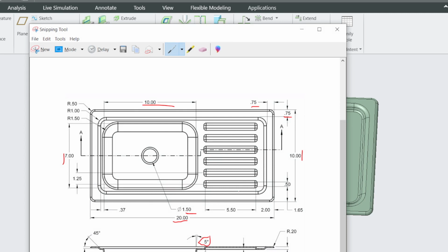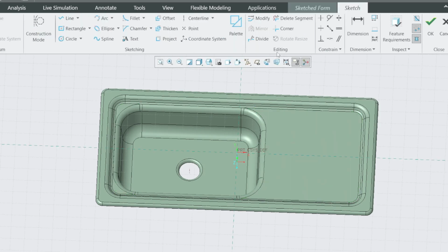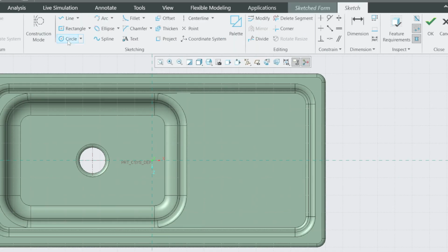Lastly is this section here, 5.5 by 0.5. Therefore, go to the form sketched here like that. I need a rectangle. Let me use corner rectangle, not center rectangle, like that. Dimension is this one to be 5.5 and this to be 0.5. Escape from dimensioning. Try to move this around.